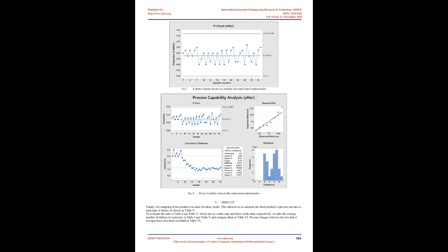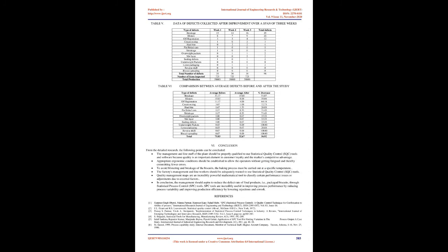Machine setup: overbaking. Improper speed and feed rate of the conveyor in the baking process. The conveyor should be programmed correctly to get the correct conveyor feed rate. Materials: an improper mixture of the materials. Erratic flow of water in the mixture. Use of moisture sensors in the process of mixing to sense extra moisture. Environment: underweight or overweight packages. Inappropriate adjustment of the room temperature. Ensuring proper ventilation.